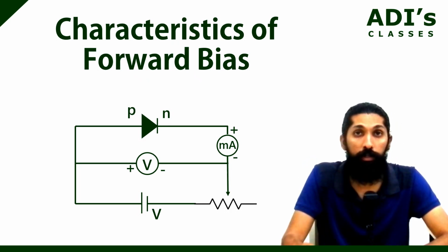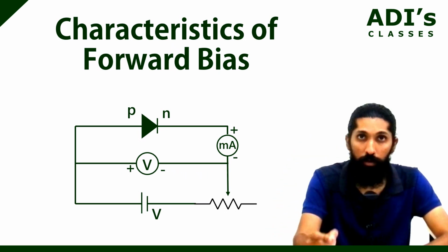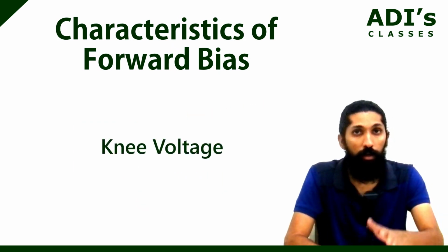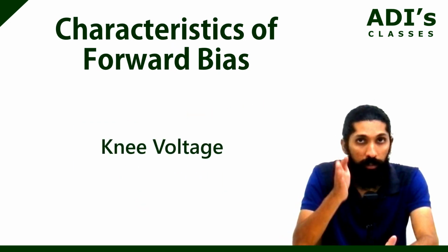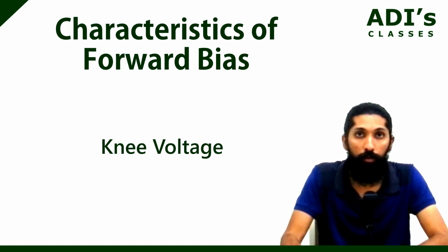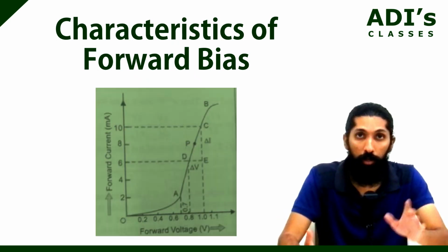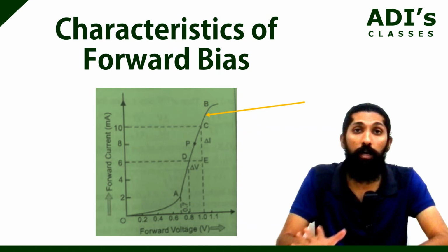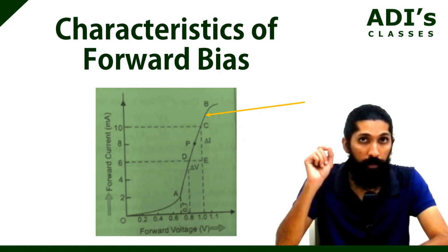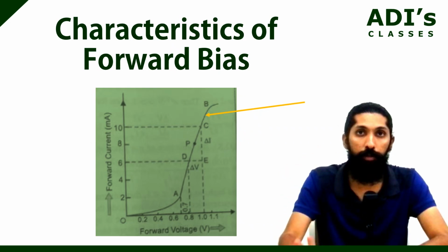After a particular voltage, the current becomes so high, this voltage is what we call knee voltage. In the sense, for a PN junction under forward bias condition, if the given voltage is more than the knee voltage, the current is going to become exponentially large. Look at this particular graph. This is how it looks. Now, you see that line? It's going to be exponential, isn't it? After the knee voltage, this is how the graph is going to be.